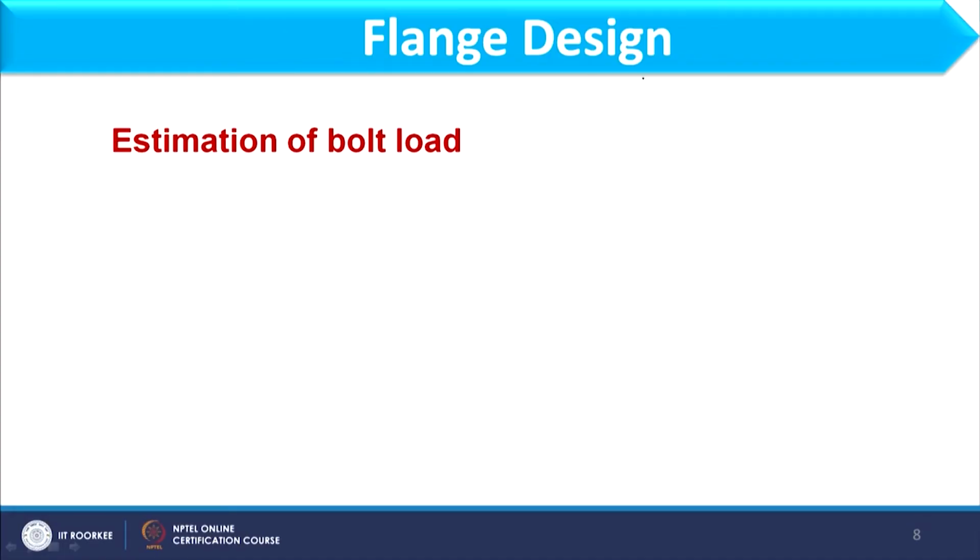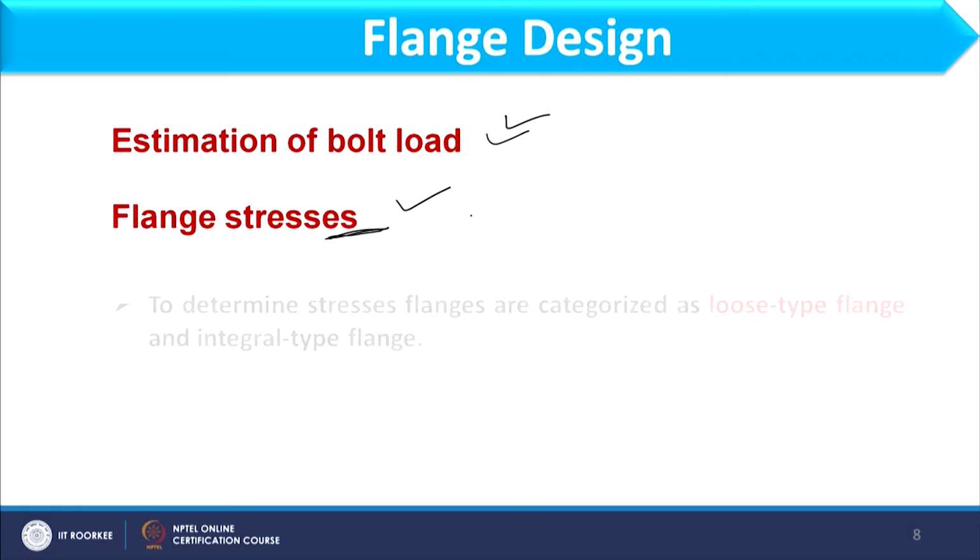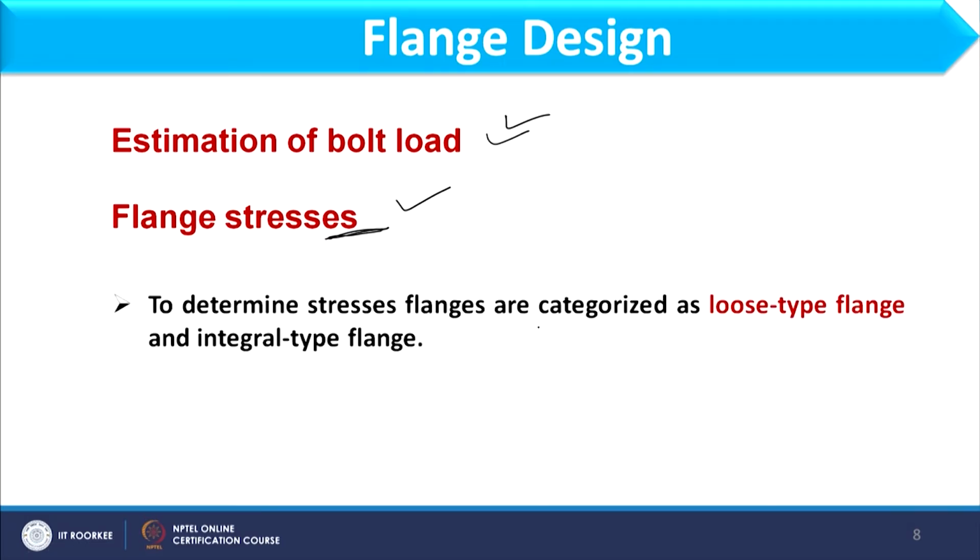Now, as far as flange design is concerned, what do I have to estimate or find out? I have to estimate the bolt load first and then flange stresses, because bolt load will speak about how many bolts are required. Flange stresses speak about how much thickness of flange to be provided. So, to determine the stresses, flanges are categorized as loose type flange and integral type flange. Now, what is this loose type flange and integral type flange?